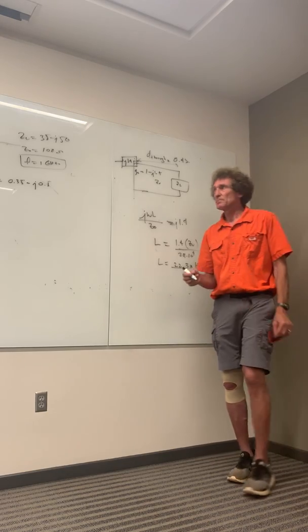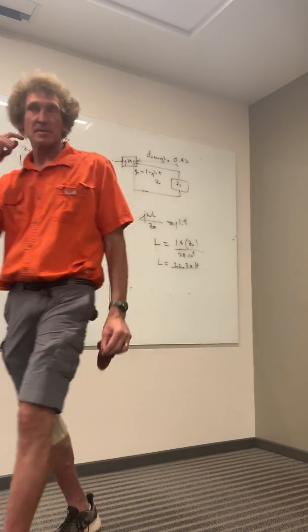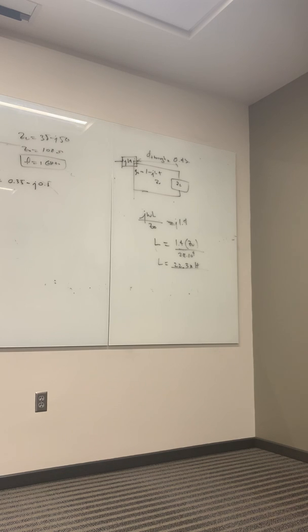That's the way to do this impedance matching with actual elements. Now, I'm going to tell you, this is tricky at high frequencies. Remember I told you about that solder ball? I was at 1.4 gigahertz. The higher in frequency you are, the harder it is to do impedance matching with an element.